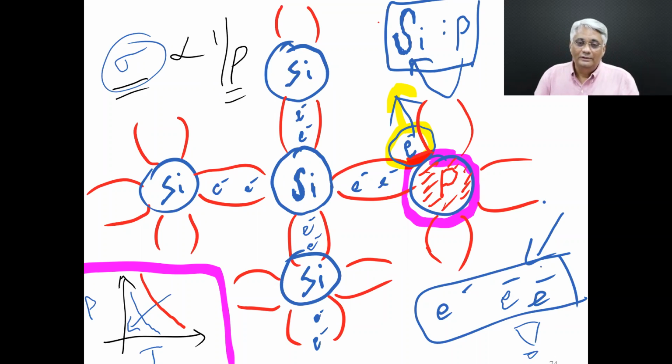That's the power of Hall effect measurement, which is a very important tool. And thin films are very much preferred for Hall measurements because, when I teach about Hall effect measurements, how you get carrier density, Hall coefficients, etc., you'll realize that the measurement of Hall voltage will be much better when you deal with a thinner sample.